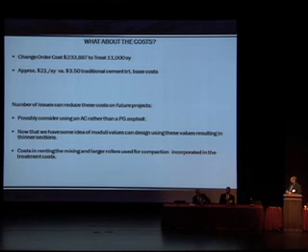Another thing that comes to mind is the fact that we didn't know what we were dealing with as far as moduli. So when we did our pavement design, it's probably a little bit conservative. With such high numbers, you can probably reduce your thickness, maybe not look at 11, maybe look at something thinner, so that would affect your cost.